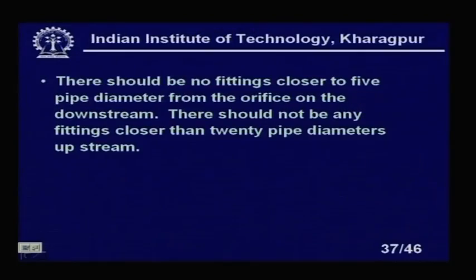There should not be any fittings closer than 20 pipe diameters upstream. Upstream is more restricted. Okay, that is what we can see.